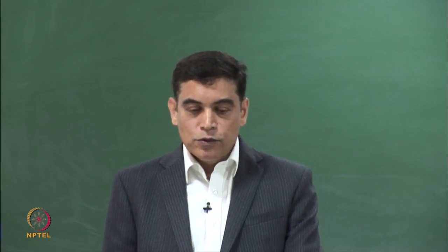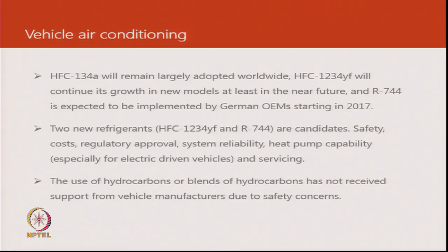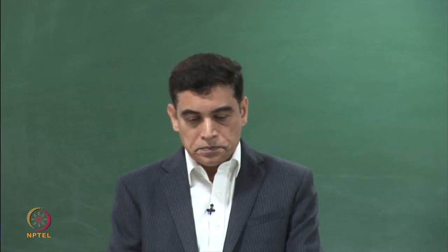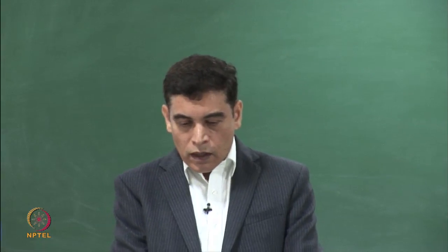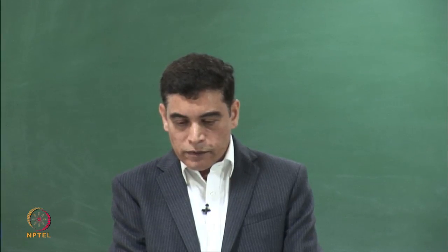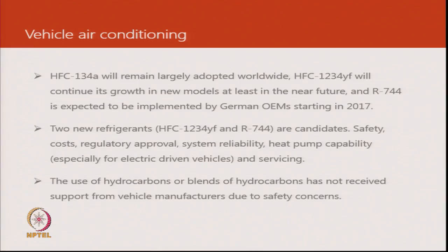And there are some new refrigerants, 1234YF and CO2, the two refrigerants which are being considered. One of the manufacturers has announced that they will be using CO2 in their vehicle air conditioning systems. That automobile manufacturer is a German OEM, and this year they will start manufacturing CO2 based air conditioning systems for their vehicles.